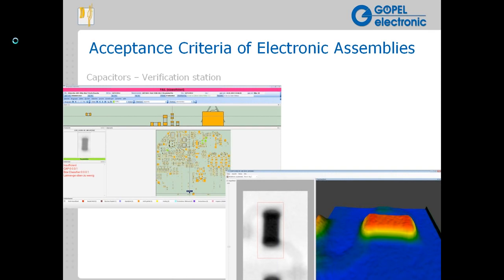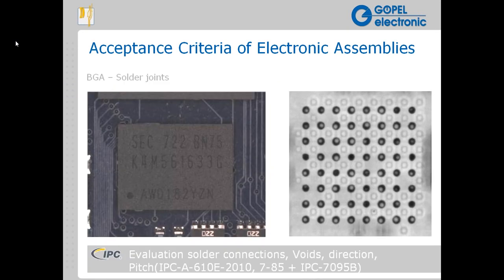In this particular case, you can see an imaged BGA and its particular balls, where we can see the shape of the balls, we can see the density of the balls. The shape of the balls gives us a lot of information that relates to the quality of the contact. In this particular example, we can see numerous voids within the solder balls, so there are a lot of detailed characteristics here that are revealed in 3D AXI.